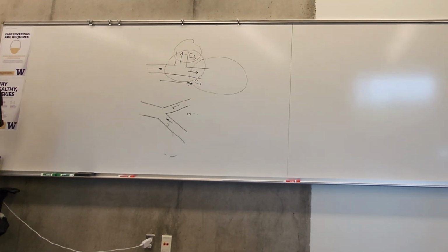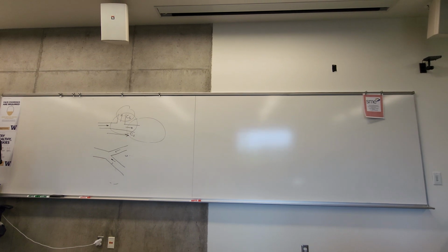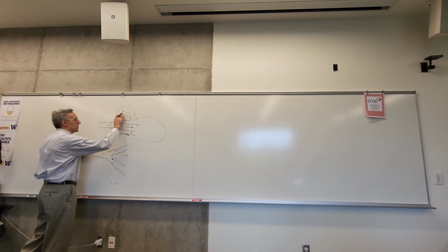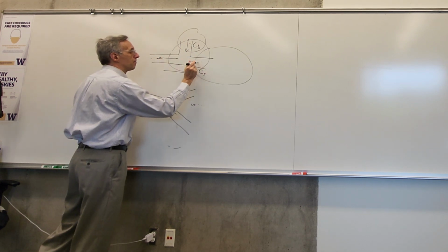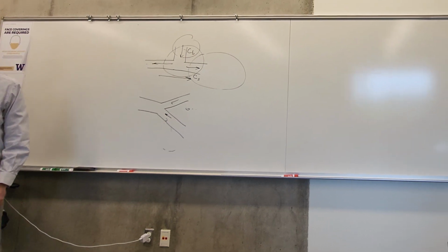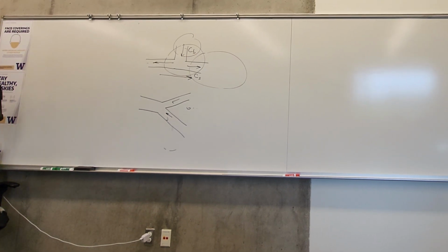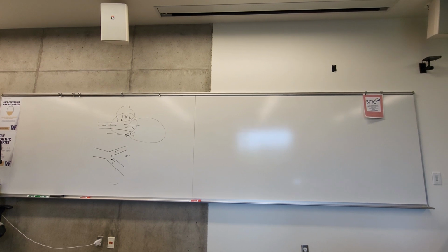We have two questions about that. If the inlet was actually on the top and split towards the sides, would we use equivalent length for both of them? Or is it a different equivalent length that we should be looking at? If the flow is just like this, then it would be different. Right. And what you just said implies that we should actually take the branching literally. Like if it goes straight, that's the straight through, and the other is the branch. Yes.